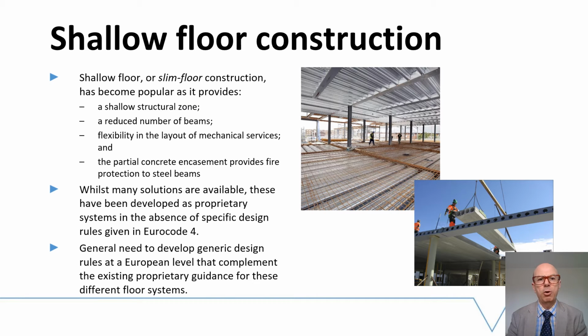Shallow floor, otherwise known as slim floor construction, has become popular as it provides a shallow structural zone. It has a reduced number of beams because of the spanning capabilities of the slabs. It provides flexibility in the layout of mechanical services because they can be positioned below the soffit of the floor. And the partial concrete encasement provides fire protection to the steel beams.